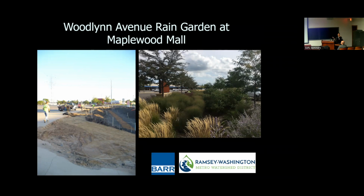So I mentioned that first iron enhanced sand filter on Beam Avenue in Maplewood. Andy refers to that one as the Minnesota filter. I love that. Anyway, after that experience, we thought, well, let's try different implementations for this. So we did a big project at Maplewood Mall, and we did a bunch of rain gardens in the parking lot there, and we put iron enhanced sand in as a strip down the middle of the rain gardens because they weren't good for infiltration.